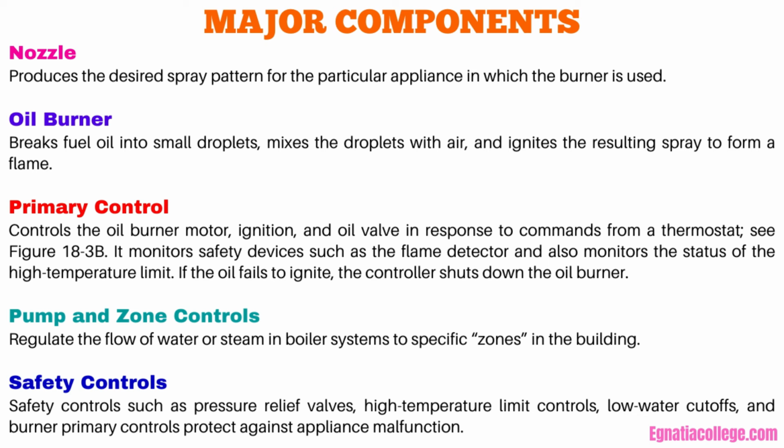Pump and zone controls regulate the flow of water or steam in boiler systems to specific zones in the building. Safety controls, such as pressure relief valves, high temperature limit controls, low water cutoffs, and burner primary controls, protect against appliance malfunction.